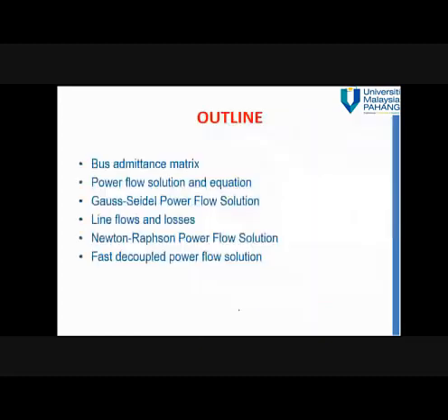Okay. So the outline for this chapter: bus admittance matrix, power flow solution and equations, Gauss-Seidel, line flow, losses, Newton-Raphson. These are the methods: Gauss-Seidel, Newton-Raphson, and fast decoupled power flow solution. These 3 methods are used to solve the power flow or load flow analysis. Okay. The first step is developing the bus admittance matrix.